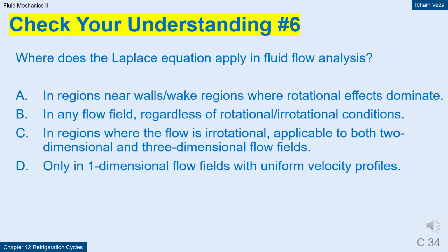A. In regions near walls or wake regions where rotational effects dominate, incorrect because the Laplace equation does not apply in rotational flow regions like near walls or wake regions. B. In any flow field, regardless of rotational or irrotational conditions, incorrect because the Laplace equation is specific to irrotational flows and is not valid for rotational flow conditions.